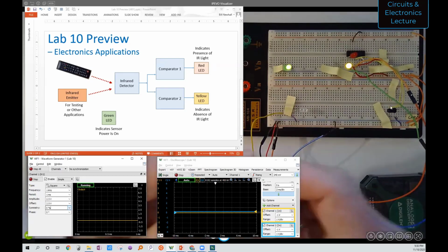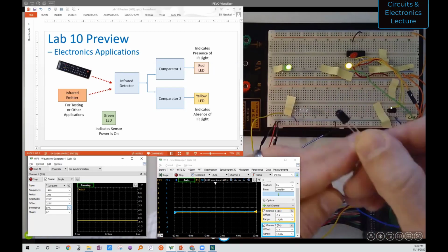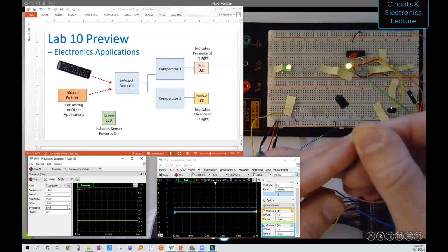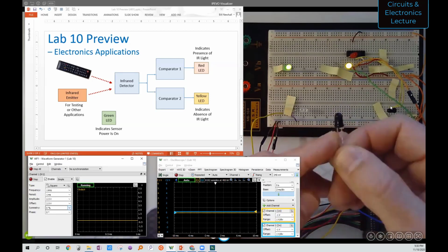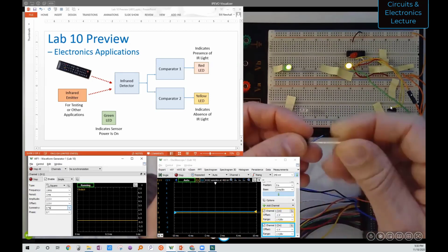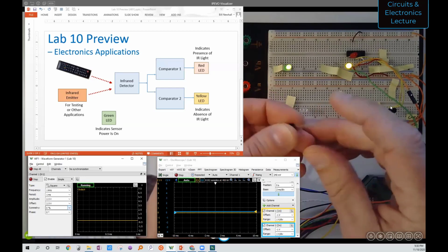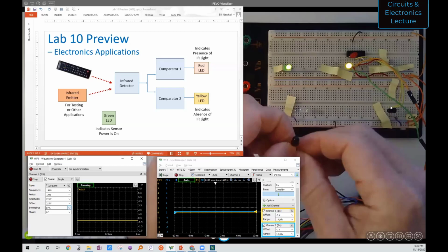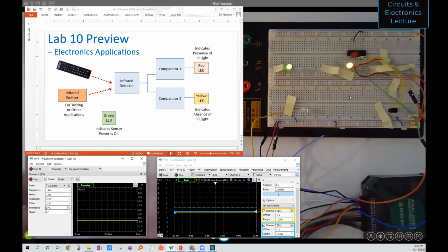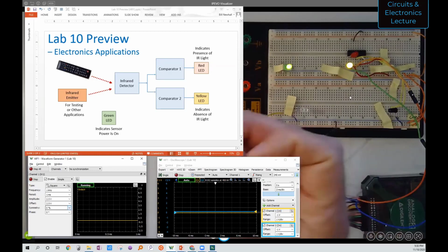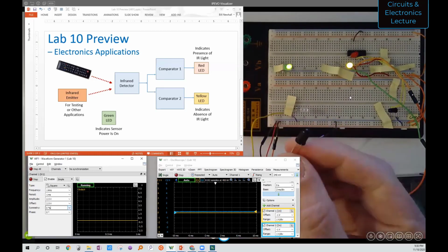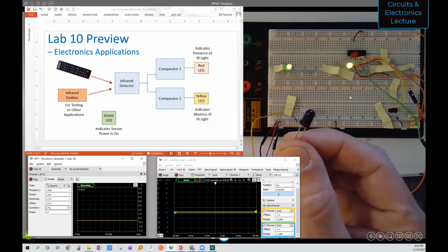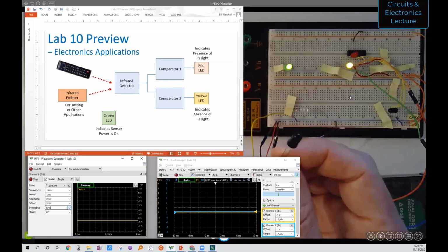So that device, if I can bring it a little closer, it looks like this. It looks like another LED, but actually it's just a package that looks black, and it has a collector and an emitter terminal on it. There's no base. The base is actually controlled by the current coming from the light impinging on the device. This device looks black, but it's actually not black. That's transparent mostly to infrared light, and it looks black because it's blocking visible light.